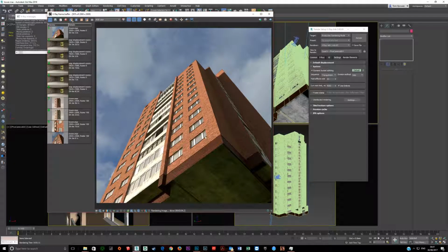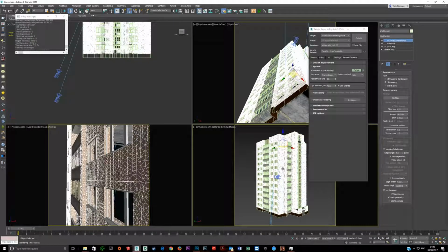It can be very important on cushions, it can be important on wood, it can be important on carpets, it can be important on a number of things. The tips and tricks of how you use it are simple. You subdivide, you put it there. You can use V-Ray triplanar texture if it goes around corners. You want to curve those corners and have them smooth around there. You don't want to be having jagged edges. You want your smoothing groups to be done properly. You want to have keep continuity checked.